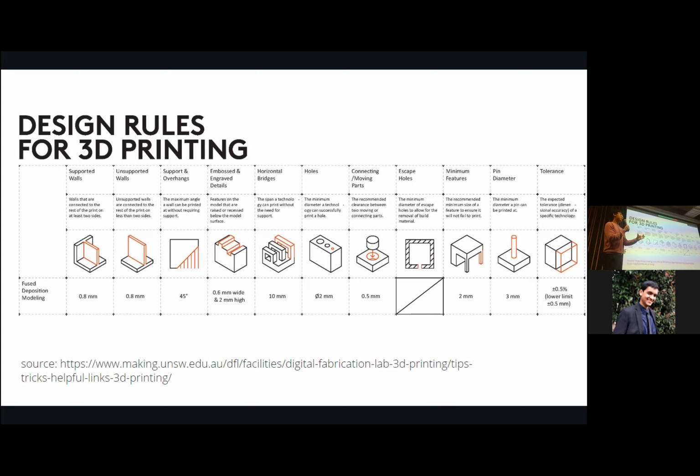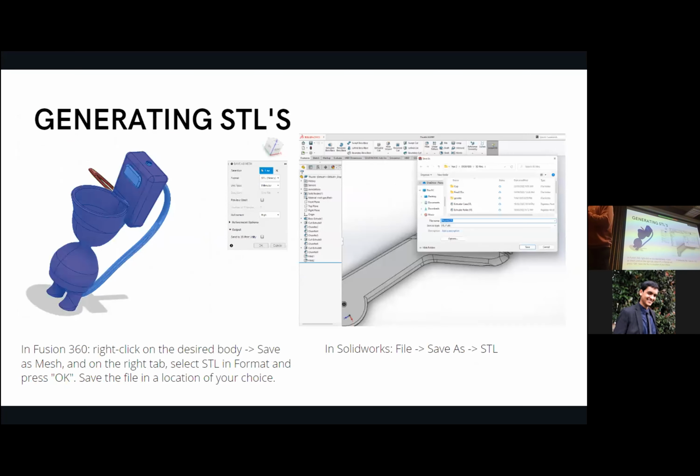Yep, you just have to make sure the features are not too tall and skinny. Otherwise, I have an example, but I can't really show it to you now. But that will create issues with the tall and skinny parts flexing when the printer goes over. But that's basically it. You don't have to worry about escape holes because that's a thing for SLS printing or SLA, and we will be sticking with the usual FDM style printing, which is straight material through the hot end.